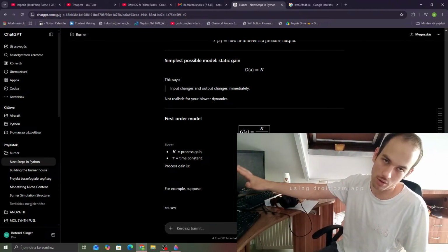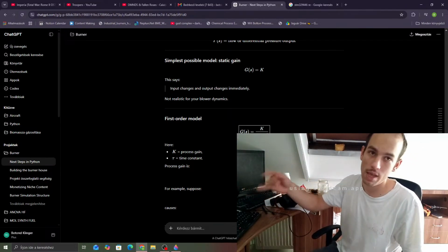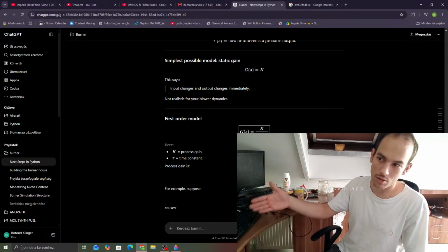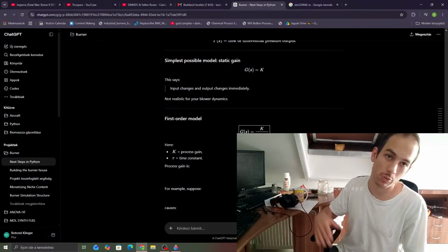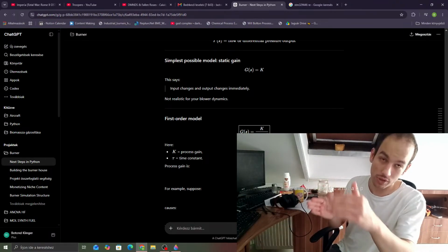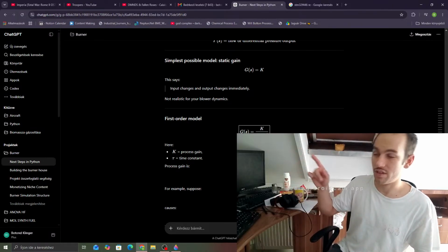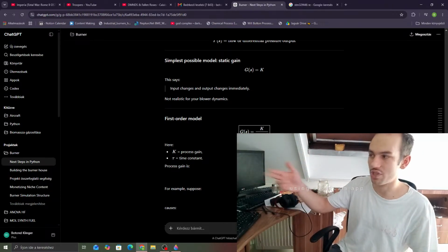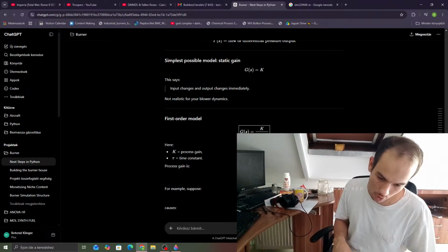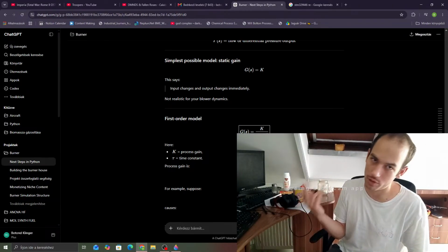This is the plot, and from the plot you can put together the transfer function, and then you can use that to make the controller. So why is this good again? Take the physical thing, measure it with step responses, then you have data points, then you can plot them, you can determine these constants, then from the constants you can create the transfer function, as well as use these constants to tune. So basically create a controller that's called a PID controller, P proportional, integral, derivative term.